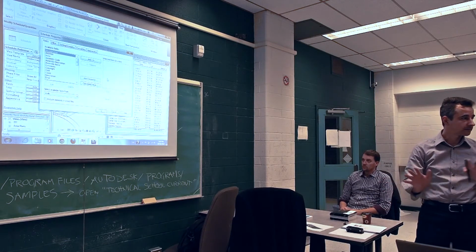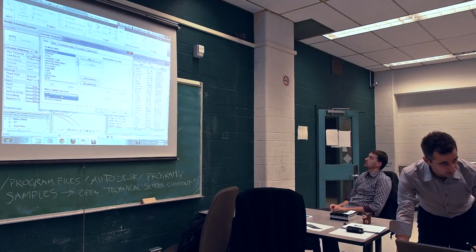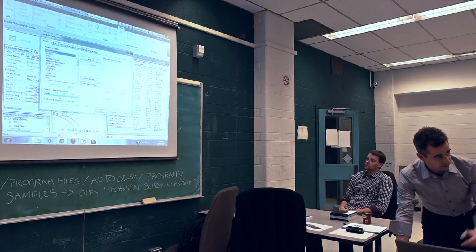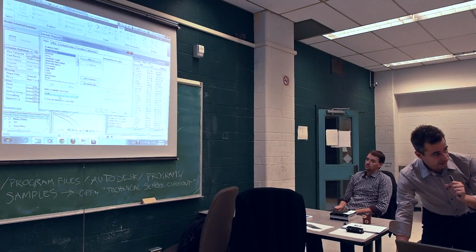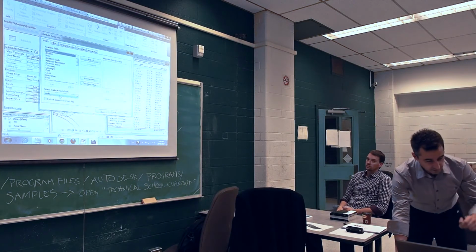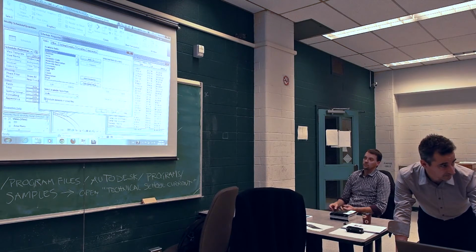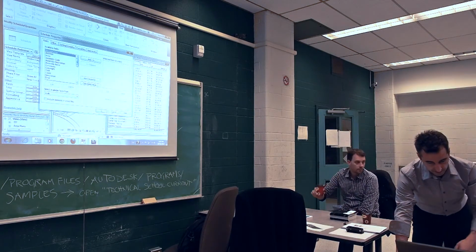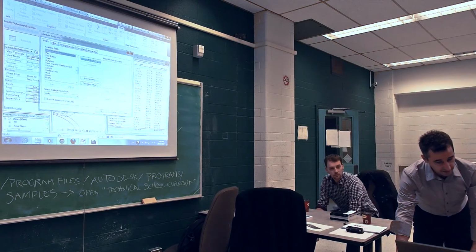We've seen this before. So, what did we see here? What do we notice? Walls. Select available fields from walls, because this is what I've selected, right? I want to schedule walls, it's going to be here. Something really important that you may want to use in real life: include elements in link files. Very important. I don't think it's the case in your project, but it's good to remember that. I'm going to take the family and type and add it here.